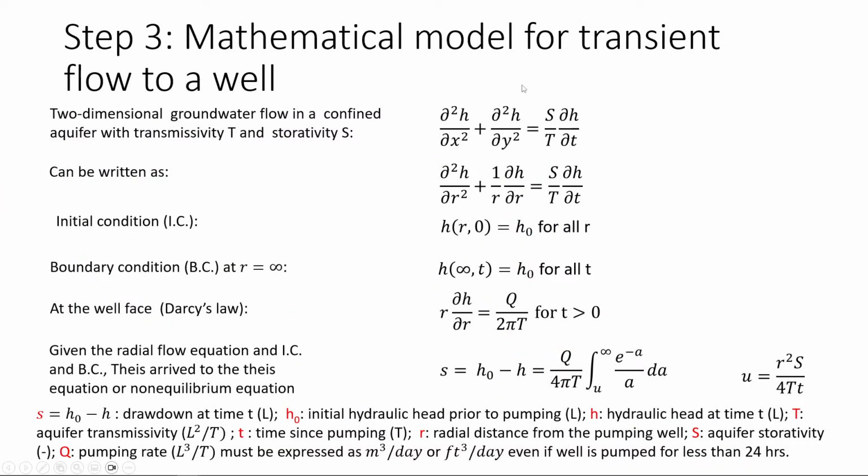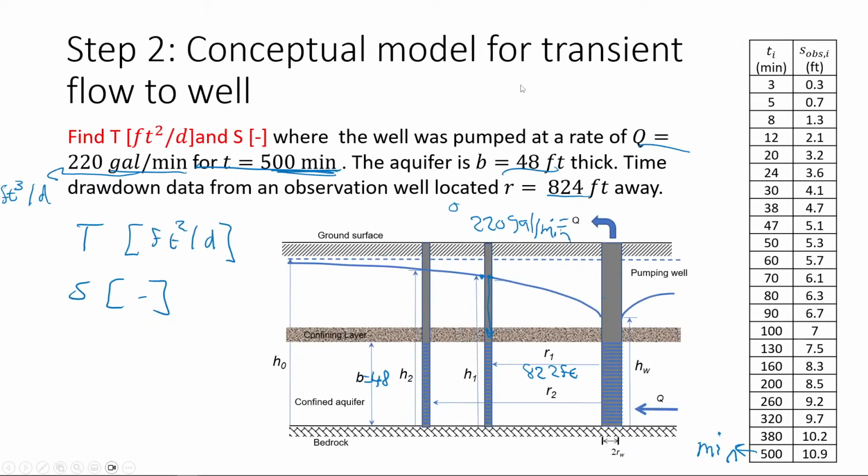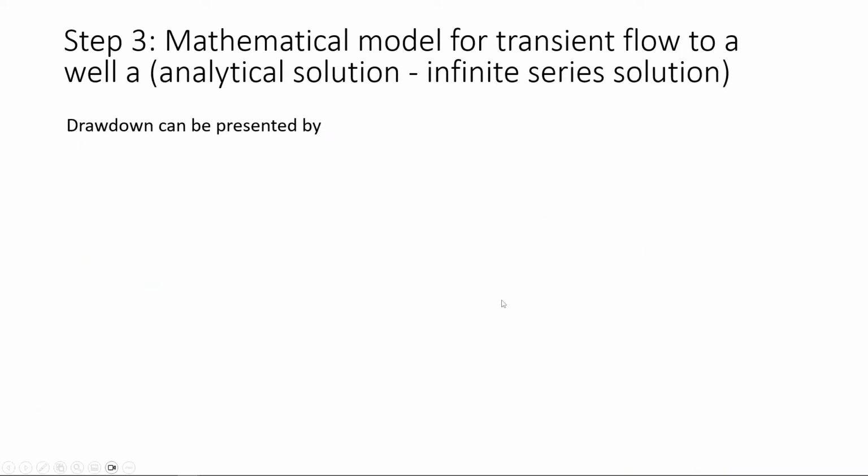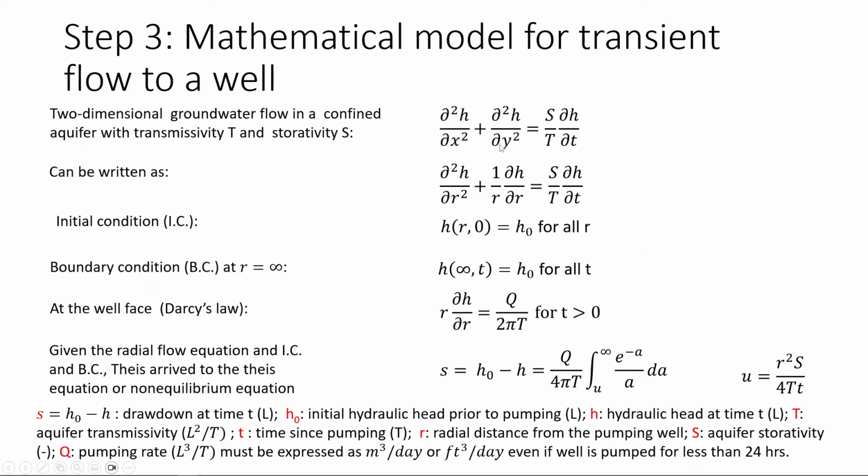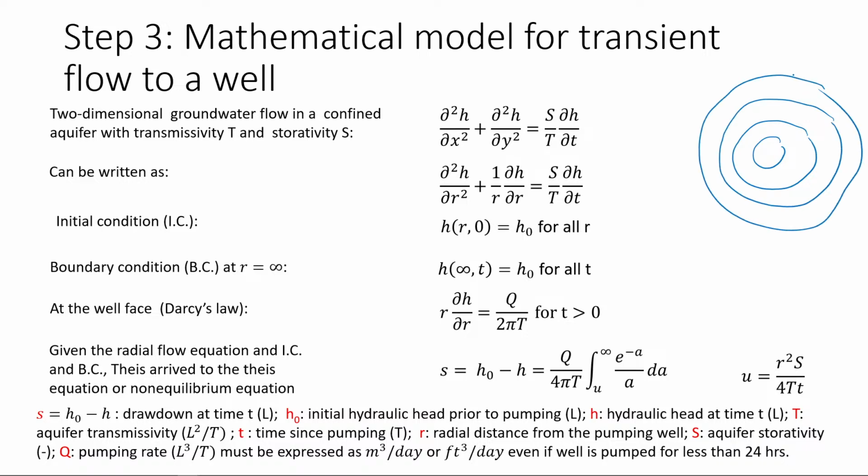This is the mathematical model for doing this. You can think of this as your head changing in the x and y directions, because once you start pumping, this is how it will evolve in time. You have these circles that evolve in time. So this is a top view. In a top view, that would be how the head will be dropping down in time.